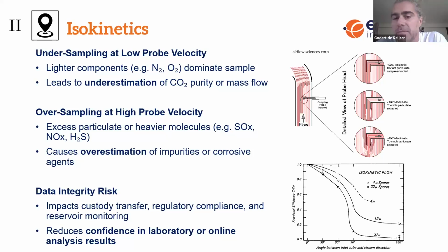And that can have significant effects in terms of underestimation or overestimation of what light components or heavy components are there. We see in different industries, so not CO2, but in oil and gas, that these can have very significant effects and really significantly impact what you are seeing in the end in your analyzer and in your samples, really significantly overestimating impurities or underestimating them.